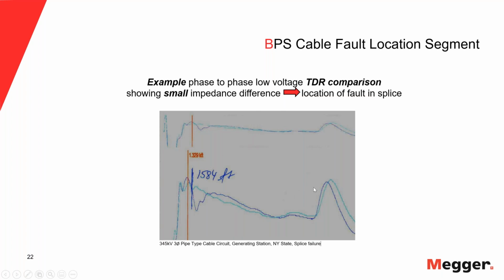So it was, I think, 8,000 or 9,000 feet of underground section up to that switch yard. So when I did this phase comparison, you can see the green line and the purple line, right? And you see clearly there is a difference. And so the one is lower impedance than the other one. The other one is pretty straight, so it probably has no problem. But the blue one certainly has a problem because it's not supposed to have a different impedance here.